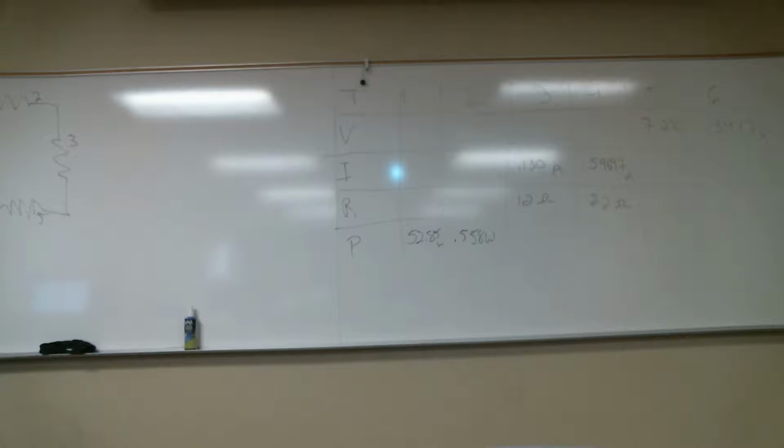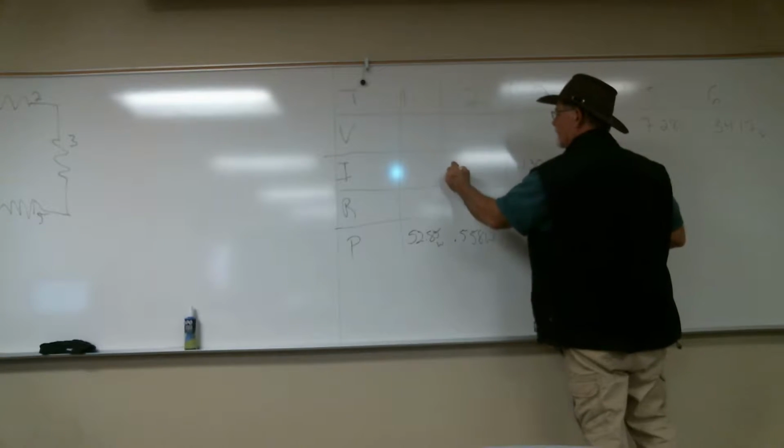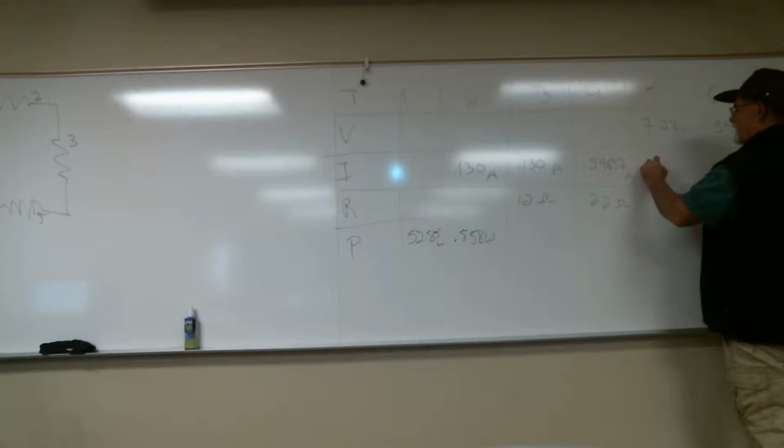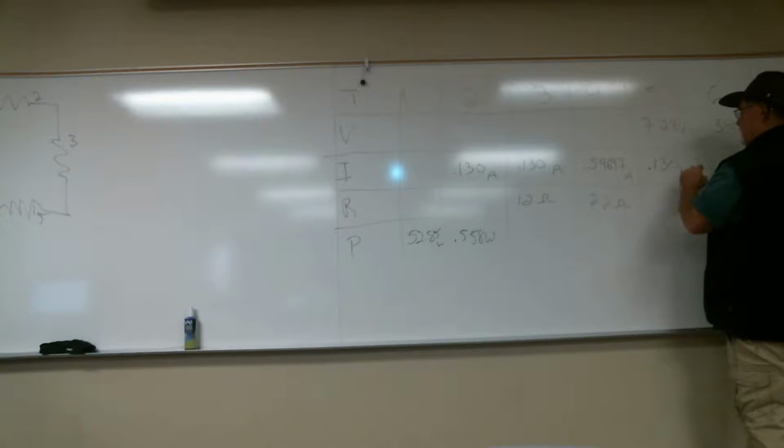So if I look at resistor 4, the current going across resistor 4, is that the same as the current going anywhere else? No, it's a part of the current going everywhere else. How about the current going through resistor 3? Isn't that also the same as the current going through 2 and 5? So I should be able to take your value 130 or 0.13 amps and plug that right into here, and where was it, 5? Without doing any other math. Okay.